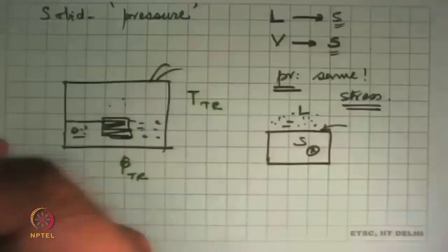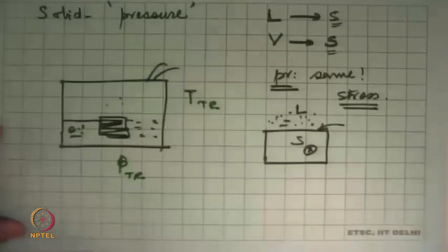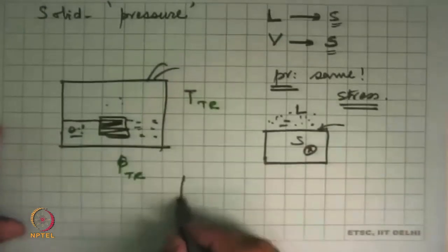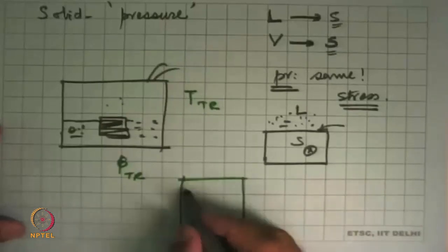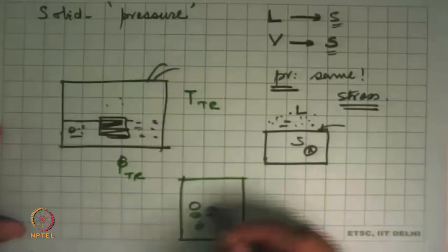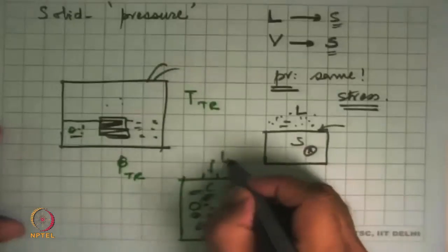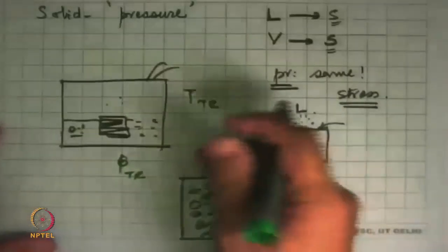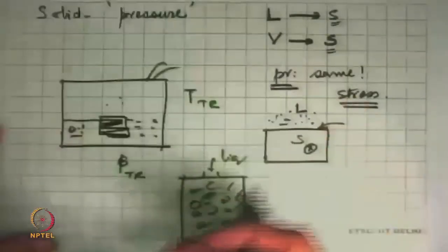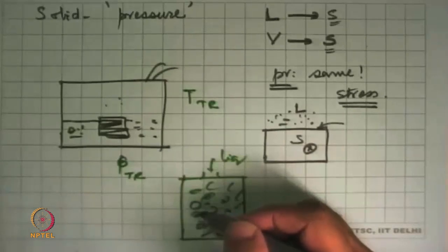And we exploit this in one very important way, not in thermodynamics but in all measurements of temperature, especially in heat transfer. What we can do, and you can do this small experiment yourself, is take a thermos flask, push crushed ice into it, pack it as much as you can, and then pour a little bit of tap water in it. What will happen? The temperature of the water, which was say at 25-30 degrees Celsius, will go down, some of the ice will melt, and if you keep measuring the temperature, you'll see it going down, to 3 degrees, 2 degrees, 1 degree.